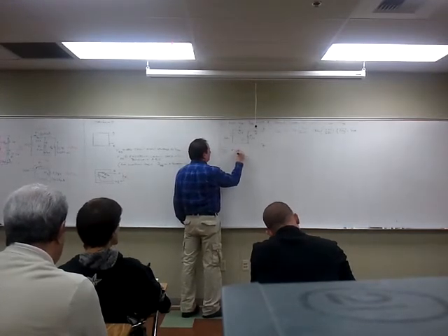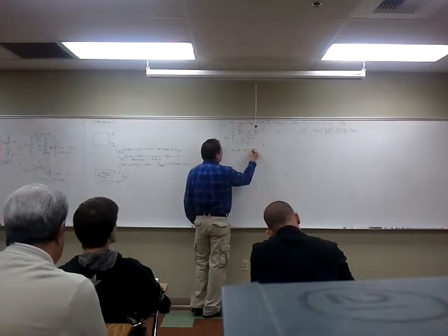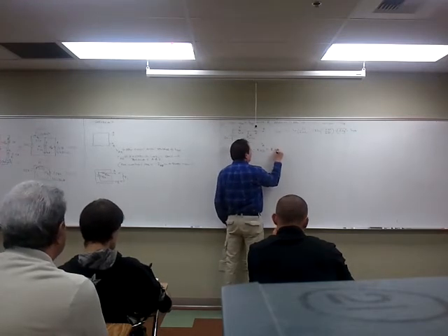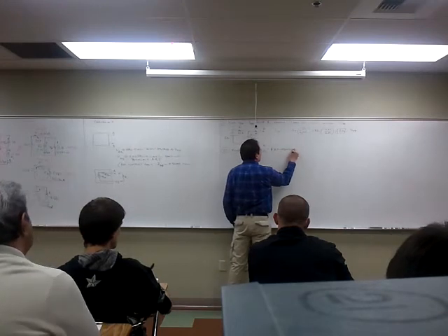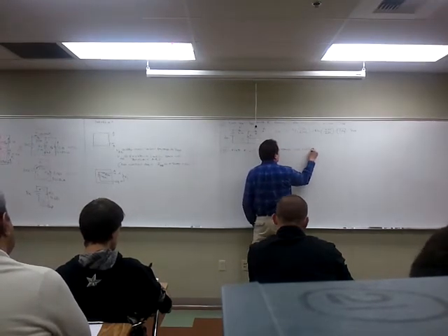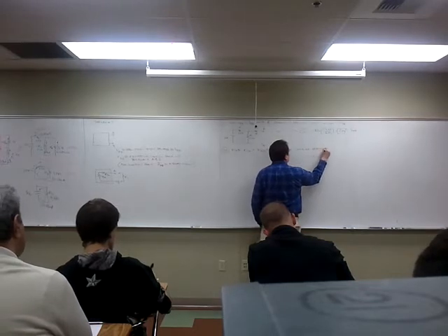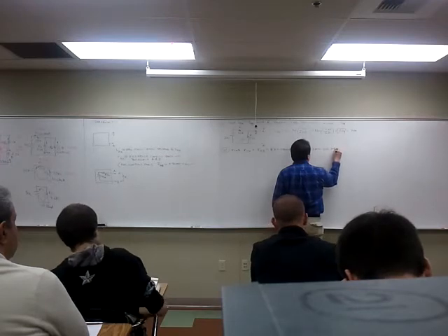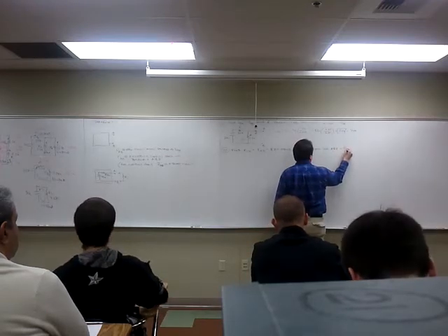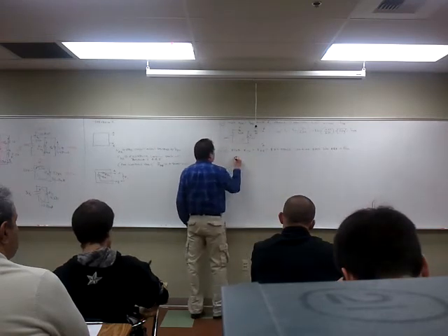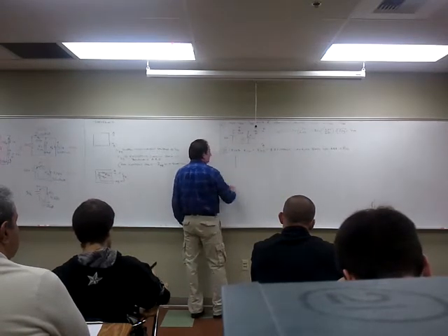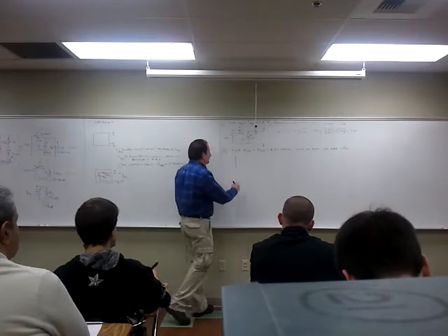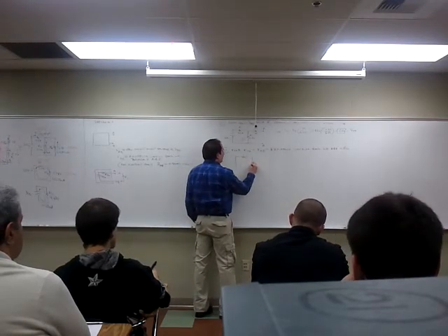Find R Thevenin, which is the resistance looking back into terminals A and B. It's RAB, which is the resistance looking back into A and B. And that is R Thevenin. So we have to draw the circuit. We replace the power supply with its internal resistance. Remember in superposition, the internal resistance of a power source is 0 ohms. With the short circuit, we have the identical circuit as above.